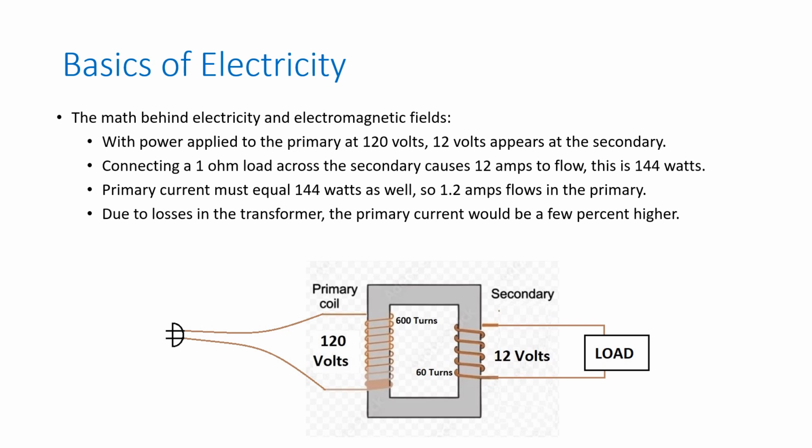which means I have to have 144 watts coming off the outlet in the house. Well, 144 watts at 120 volts is only 1.2 amps. So you notice there's a 10-to-1 voltage ratio and a 1-to-10 current ratio going on. Now, look at the fourth bullet.